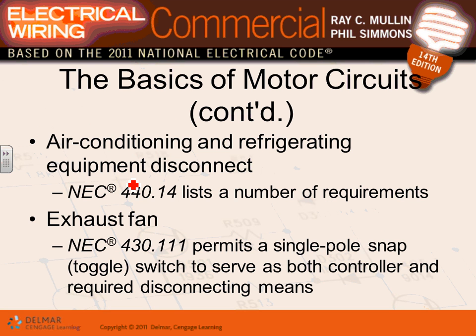Okay, air conditioning, all your air conditioning, guys. The condensing unit, which is air conditioning, has to have a disconnect provided by the manufacturer, or in our project, Derek, what did you do? I told you to throw a disconnect right at the equipment, right next to the equipment. It has to have a disconnect, rated to handle the energy used to power this equipment, as well as the current that's going to go through this equipment.